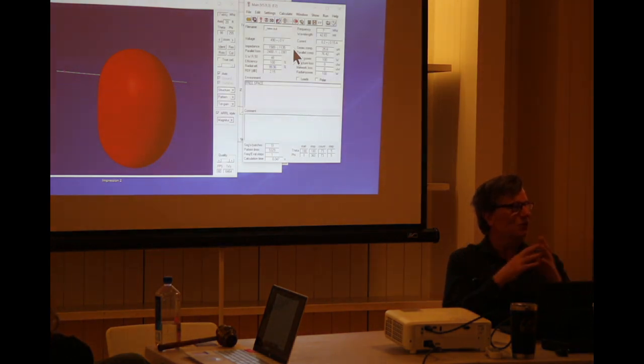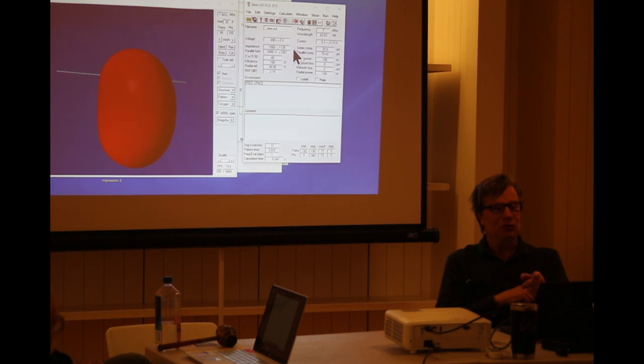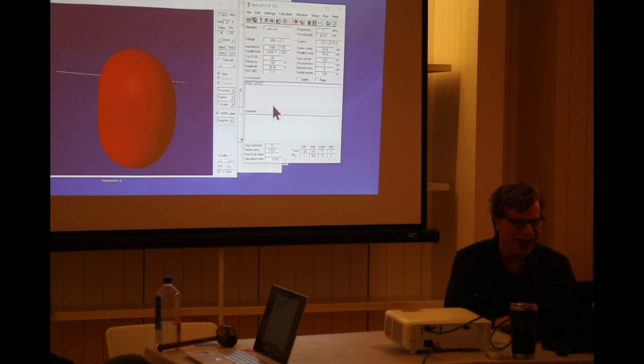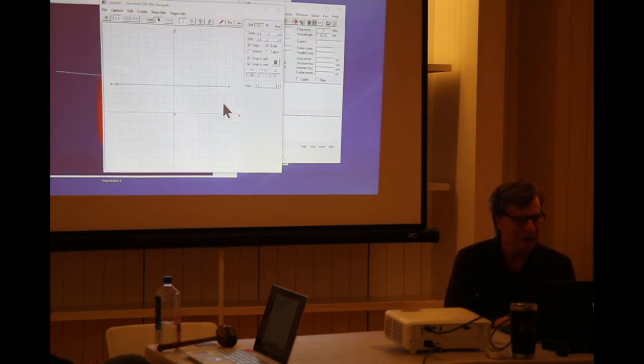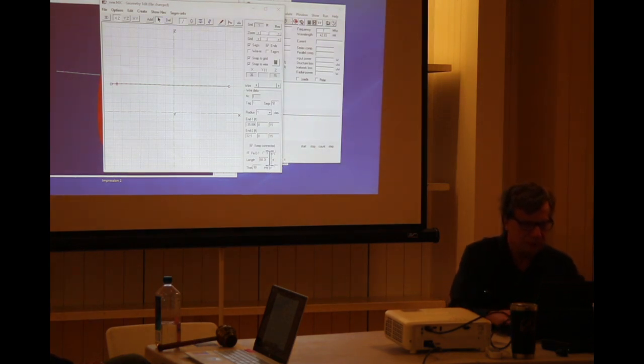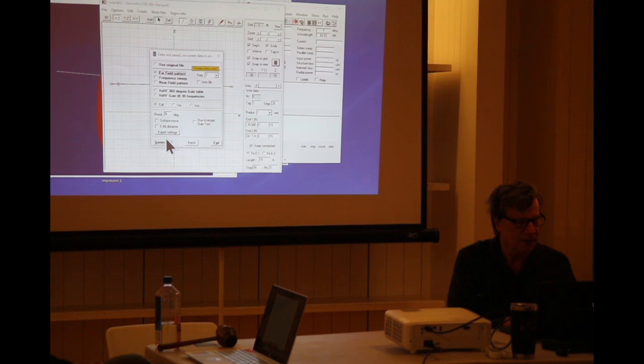Because the longer you go, you're going to lower the resonant frequency, and as you lengthen it, you're increasing inductive reactance. But since we're looking at the anti-resonance point, if we stretch this out, somebody write this down, minus 1135. So let us stretch this out. This is currently 68 feet. Let's go to 70 feet and calculate this again.